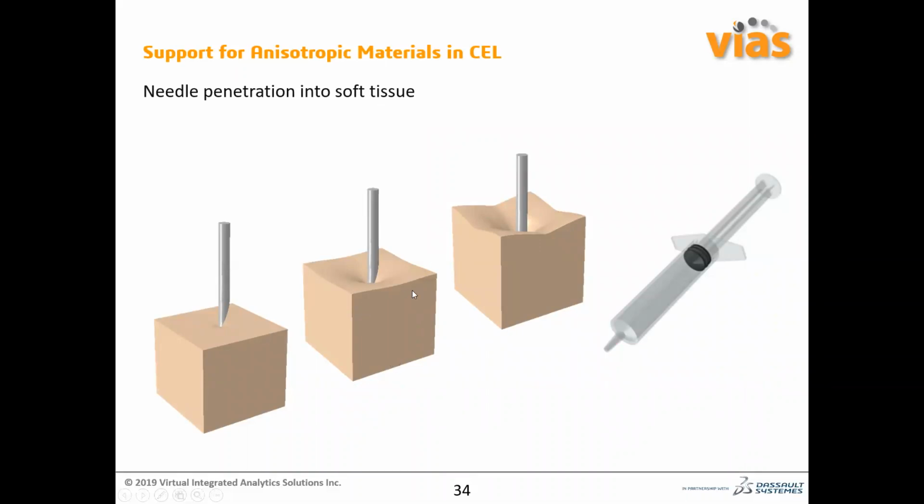So soft tissue actually behaves in a very different way. You are modeling the soft tissue using the CL technique, and the added bonus is that the algorithm is for mapping the material orientation for the anisotropic material. So the soft tissue will be having an anisotropic material, so we are adding that on. It will also have a hyperelastic kind of response, like it can have a huge deformation.